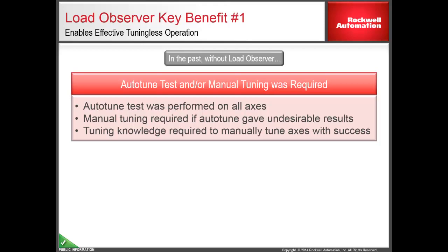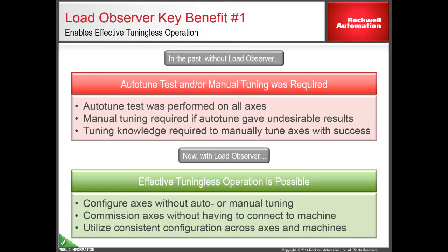Load Observer enables effective tuningless operation in many applications. In the past, prior to Load Observer, it was recommended to perform the physical auto-tune test on all axes when feasible. If the auto-tune test gain settings resulted in unsatisfactory performance, manual tuning was required. Now, with Load Observer, there is no need to perform the auto-tune test or manually tune most applications. This means that in many cases, there is no need to connect to the machine to commission the axes.